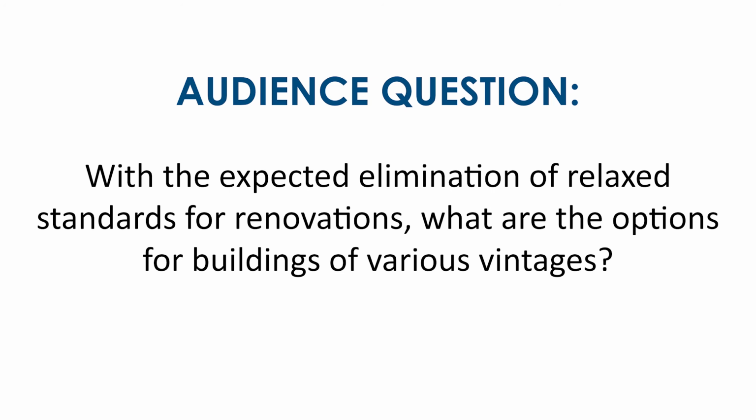And then thirdly, what we have seen in both the utility work we do and in the SB2030 work, as long as you're touching two of the three major systems, lighting, envelope, and HVAC, in general, we don't see a significant difference in the performance of new or existing buildings. Historic buildings are probably an exception, but if it's just a standard renovation, the average renovation, they can get to the same typical outcomes usually. The envelope, again, historic, totally uninsulated would probably be an outlier on that, but as long as there's some insulation with HVAC and lighting, you can often get close to the same point.